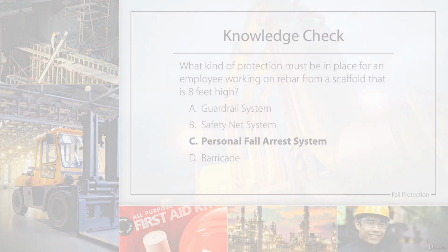Personal fall arrest system. In the case of scaffolding, it is important to note that employees must be working with a PFAS when working on framework or rebar, and all rebar that is protruding from the surface must be covered or capped to avoid any impalement injuries.